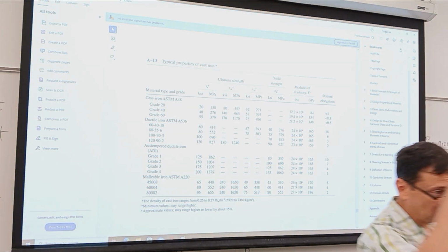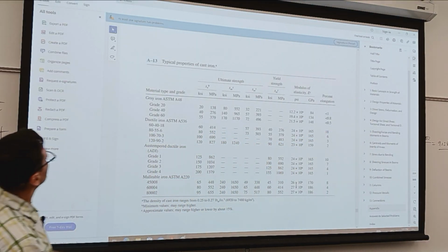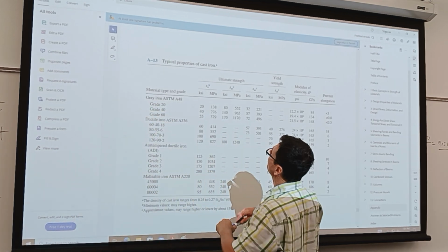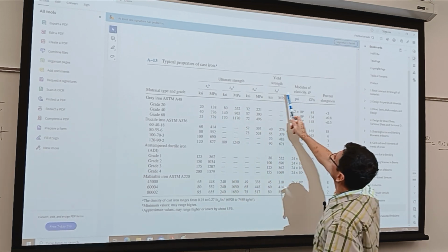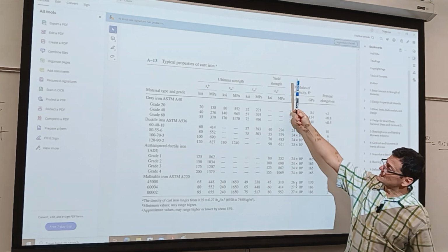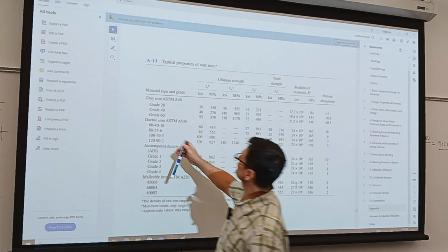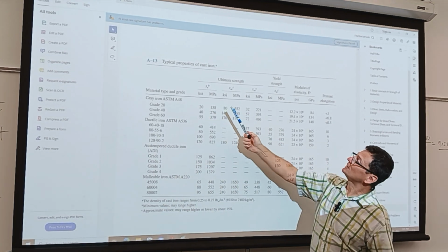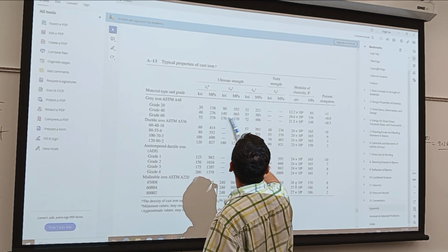You add silicon to the iron, and you get various types. So you see here, like gray iron. This is the most ordinary of the irons, with low mechanical properties. You don't see yield strength here. Iron is, for the most part, brittle, though there's some where it says ductile iron. It has different properties, and you can see compression and tension, all right?